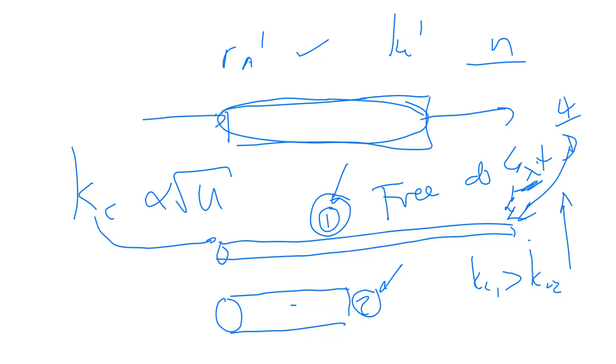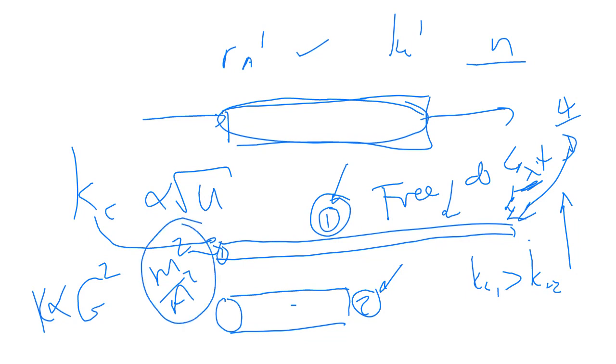But in terms of pressure drop, if I think about G squared, that K value of mine is directly proportional to G squared. And G squared is the mass squared divided by the area, so it's some form of a superficial velocity that flows in that tube. So the smaller the diameter, the higher my K value and the higher my pressure drop.